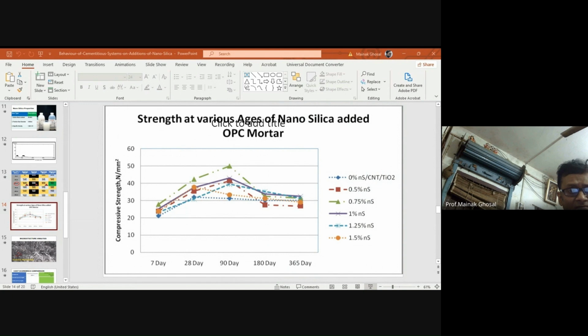And I find a 10 to 11% decrease in total cost in my colloidal nanosilica composite compared to the silica fume composite, because 34.26 kg of silica fume was added in that paper, and I added 4.28 kg of nanosilica to produce 1 meter cube of composite. So 4.28 and 34.2, so much less, and that's why the cost economics came into picture. The mix could be made at a much lesser cost compared to the silica fume composite.